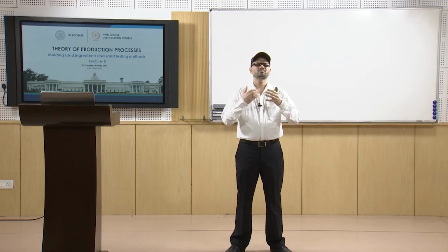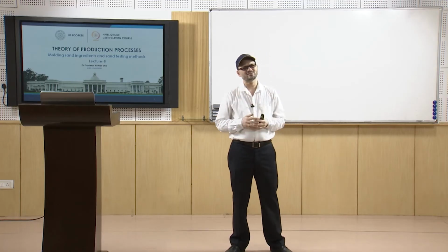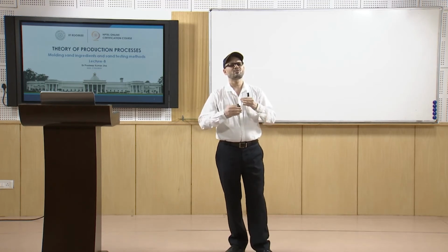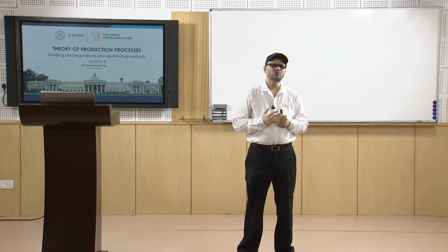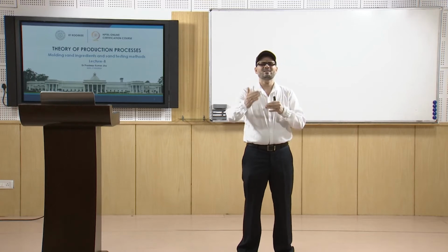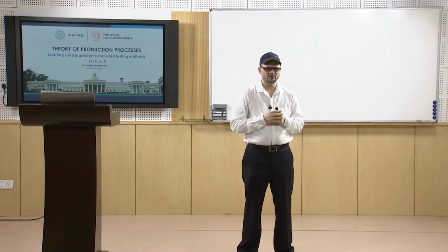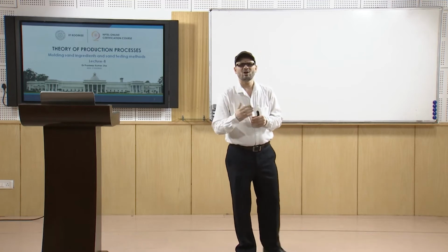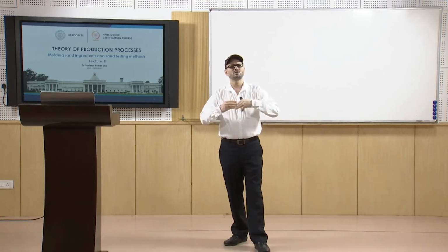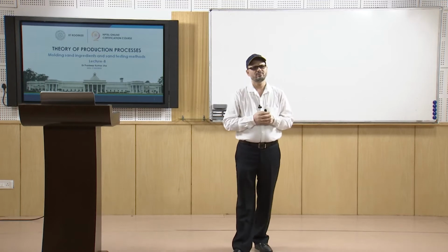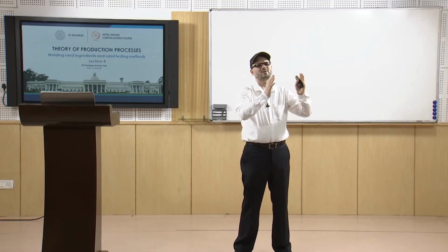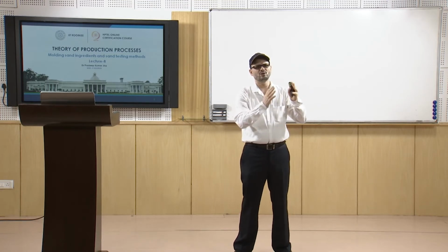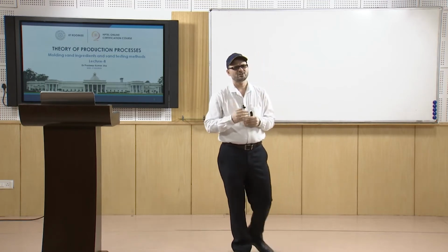In many of the molding methods where we use sand as the molding material, we may require a large amount of sand, and in many methods we require a low amount of sand. So, basically it depends upon what kind of method we are using. If we use normal green sand casting, we may use more quantity of sand, because more sand will give enough strength to the mold to withstand the metallostatic forces.